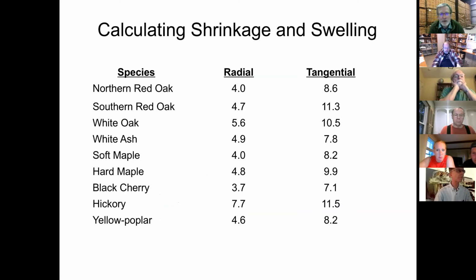One thing I'd like to point out right now is, when we buy oak, and we buy red oak, we typically say, hey, I've got a piece of red oak. But notice in red oak, there's actually 12 species called red oak. And the lumber is typically sold as red oak. Notice the tangential shrinkage value between northern and southern red oak. It's pretty significant. And we'll see what that could potentially mean to us. But sometimes knowing the exact species you're using can be very helpful, because southern red oak is less dimensionally stable than northern red oak, but when we buy boards, it's just called red oak.